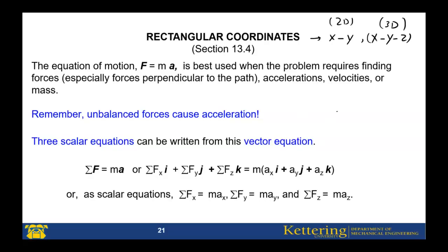Do you remember that box I mentioned to you? There is an applied force P. It has an angle of 30 degrees. I found the components of the force along x and y. I can write this P vector in vector form as P cosine 30 i plus P sine 30 j.